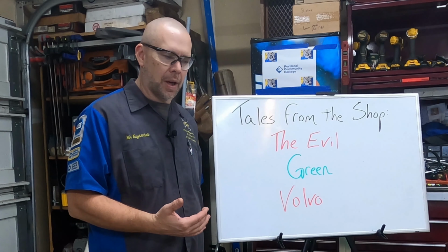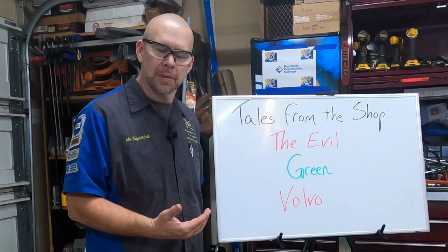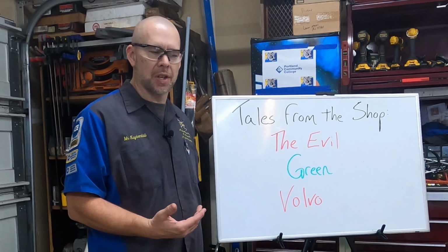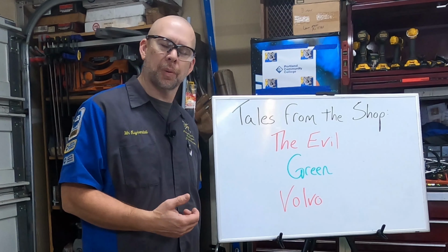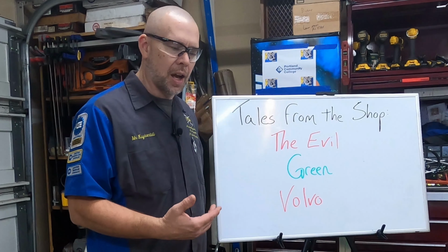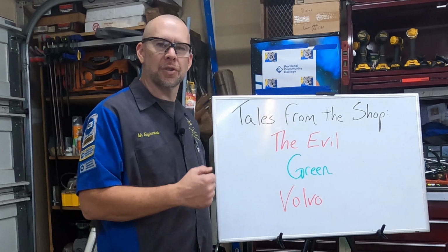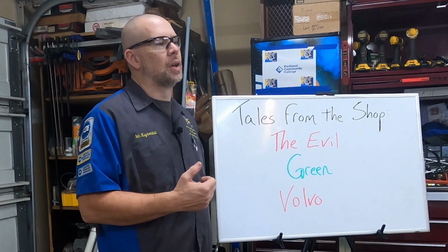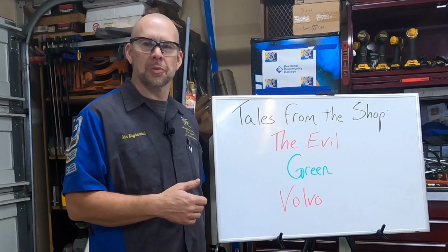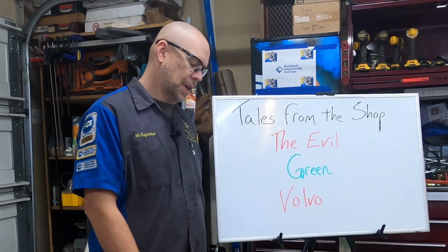So I check with him. I said, well, you did both fuel pumps, right? Because what normally happens is the pump in the tank, the transfer pump, usually dies. And then that means that the high pressure pump has to work too hard. Nope, the customer didn't have the money for it.